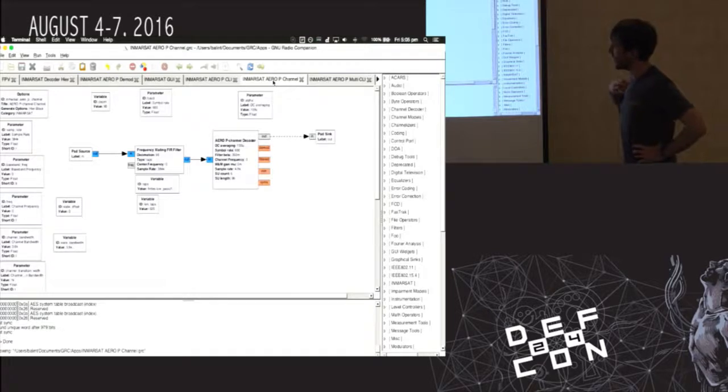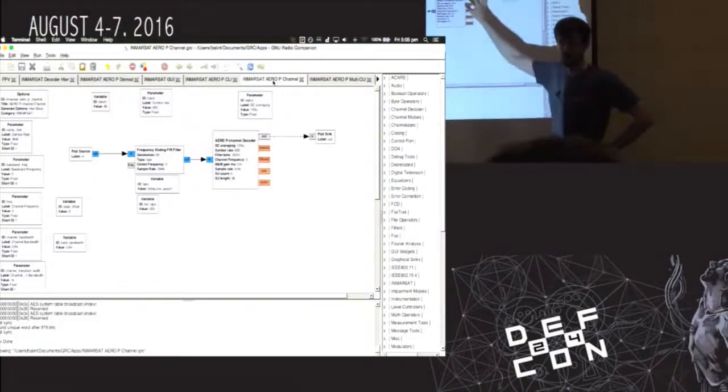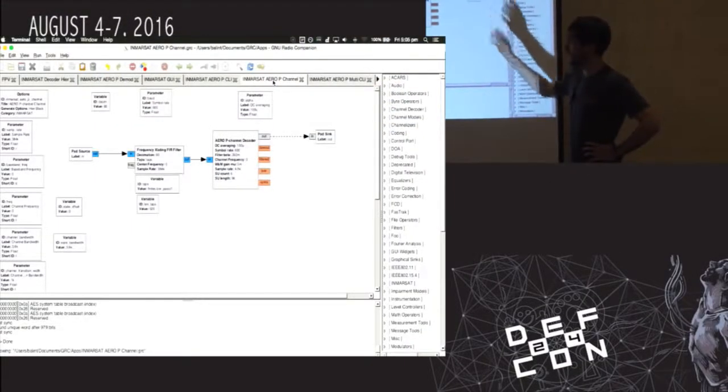But in this case, you can consider this approach as well. What I've done here is create this template. We have our baseband coming in from our receiver. We translate that to the frequency where our channel is. Then we plug it into our P-channel decoder as we had before, in that single instance of it. And then we send the messages back out. That's all it is: move to your channel and then decode it.